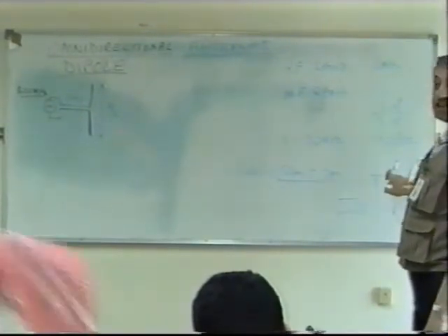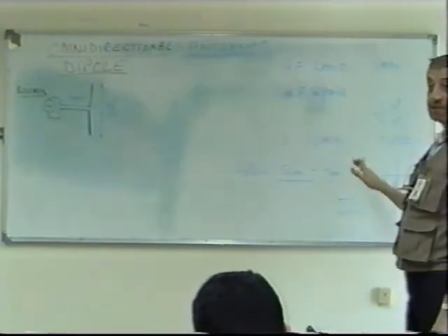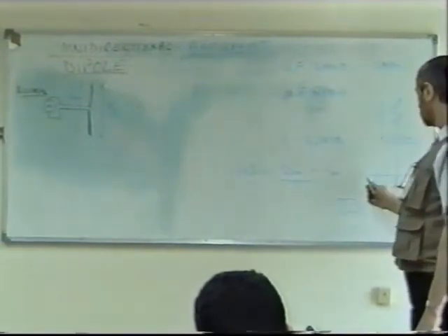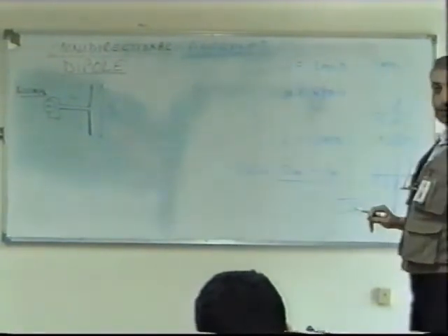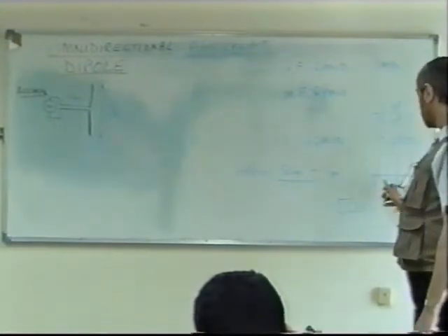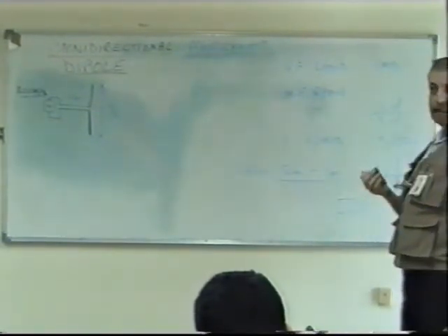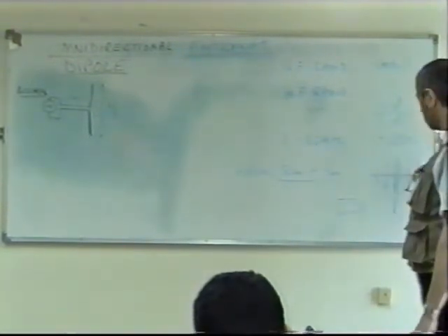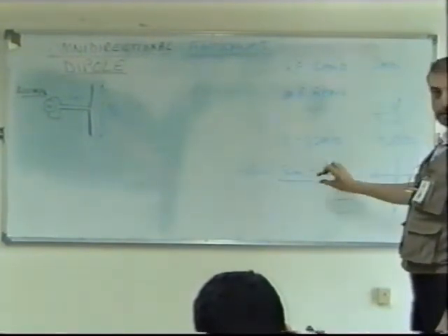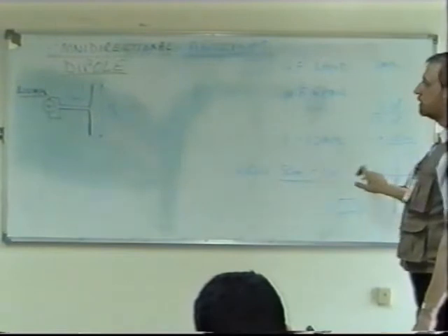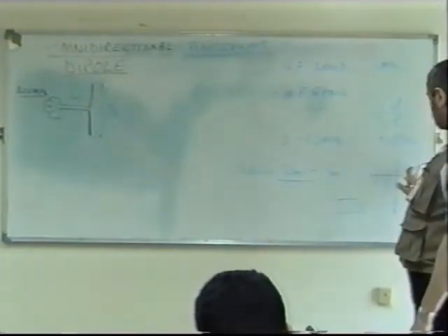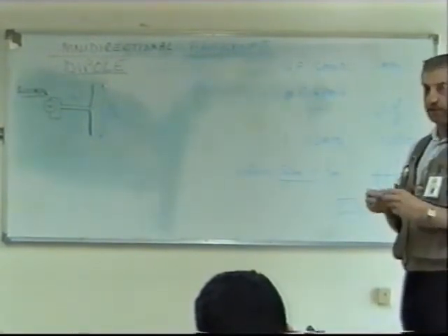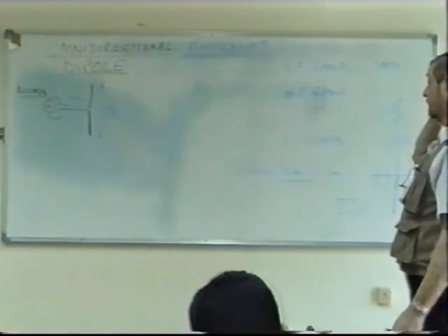That's right. Don't forget, in HF they need to cover a wide range of frequencies, don't they? To maintain communication to a certain distance. So the antennas are quite complex. The antennas that they use there are built so as to handle a wide range of frequencies. In its simplest form, the easiest way to think of the way the antenna works is to think of them as a number of dipoles, each of a different length, right? But they're all connected to the same transmitter. We don't switch between these, they're all connected, and it produces what is called a broadband antenna, an antenna which is efficient at any frequency within the HF band.